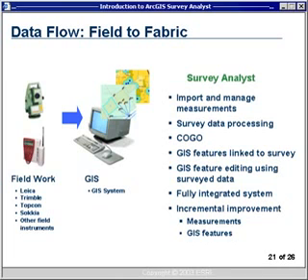The last thing I'd like to talk about on this slide is that it supports incremental improvement. And it supports incremental improvement in really two areas. The first area is the measurements. By supporting incremental improvement in measurements, it means I can load survey data into my GIS system using Survey Analyst as the data becomes available. So I can have project folders. As projects are completed, I can add the data. It also means that if a survey is resurveyed and new coordinates for a particular survey point are available, I can go in and improve the quality of that particular survey point within my measurement database.